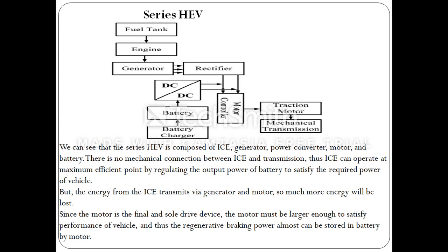What is series HEV or hybrid electric vehicle? So the figure of series HEV is as shown here. So we can see that series HEV is composed of ICE, generator, power converter, motor and battery. There is no mechanical connection between ICE and transmission.